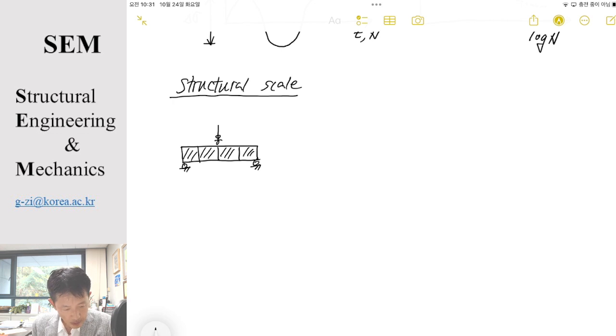Okay. And then another type, that's what we are currently doing. We are doing a fatigue test for the grout joint for offshore wind energy support. So we put the shear connection stud here, and then we have another circular tube, and this circular tube is supported here. And then these two tubes are connected by means of grout. Then we apply load here.